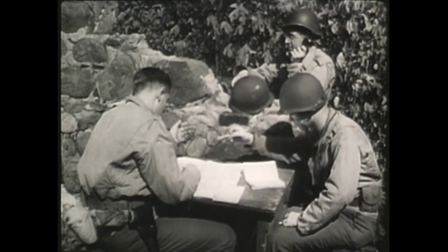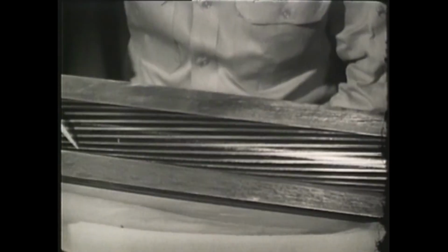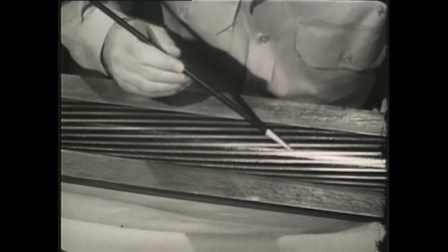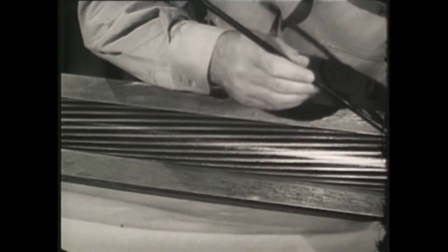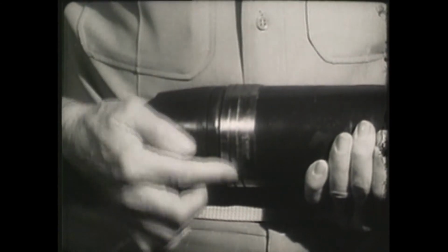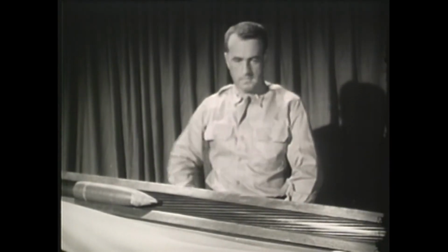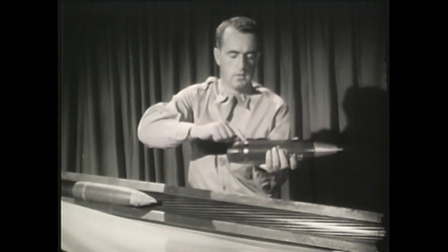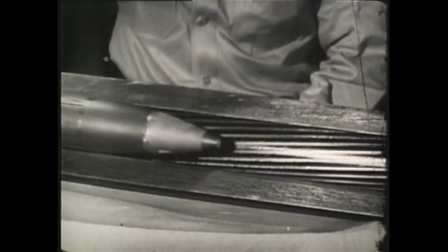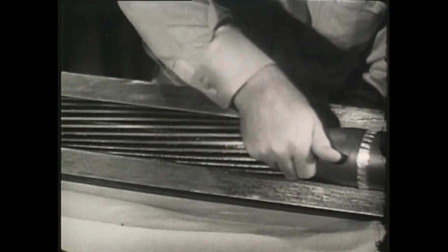This, however, causes the projectile to swerve from a straight course, drifting to one side according to the direction of the spin. That isn't as bad as it might seem because we know it's going to happen, and we allow for the drift in aiming. To get the required spin, spiral grooves are cut in the bore of the gun and a soft rotating band put around the projectile. The band engages the grooves and the projectile rotates or spins.